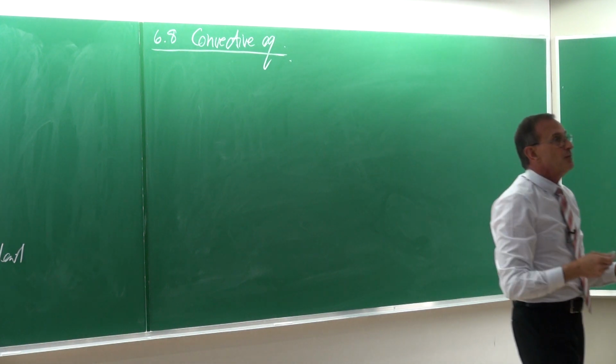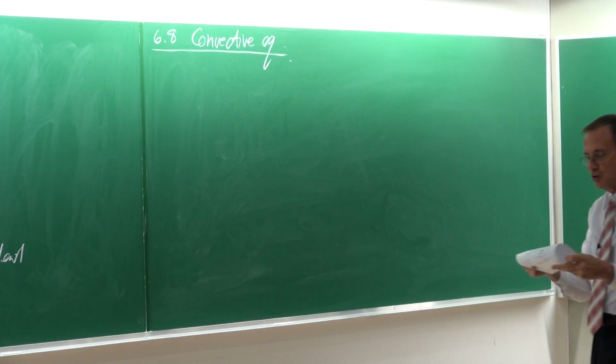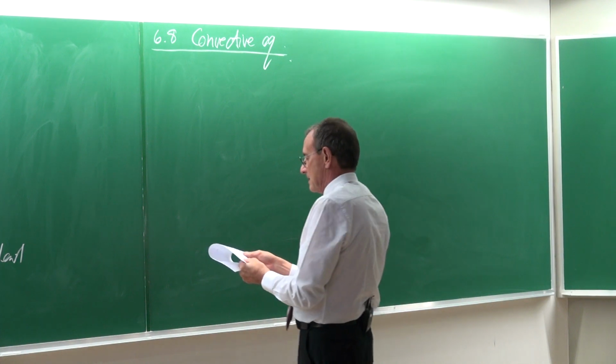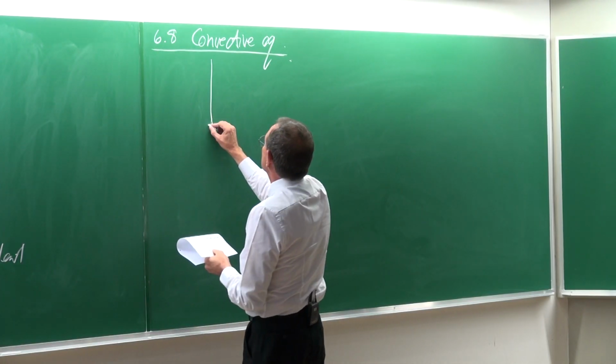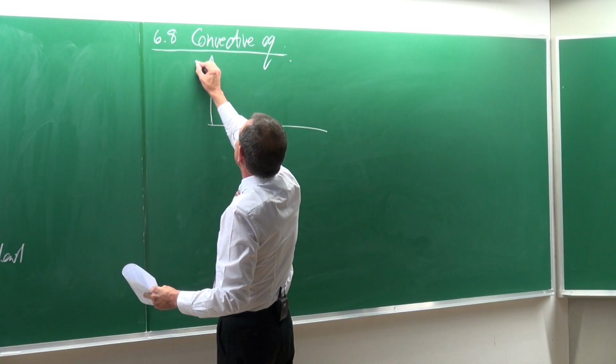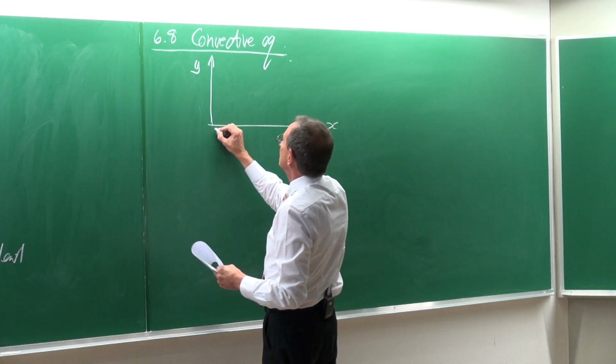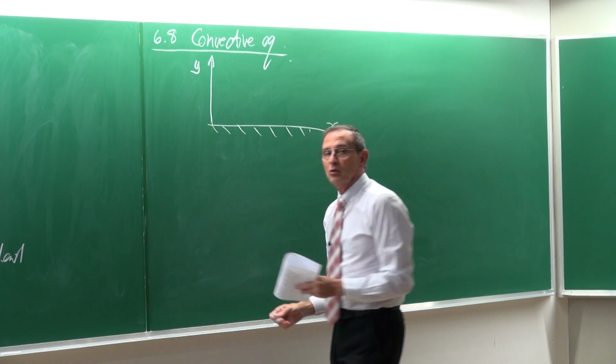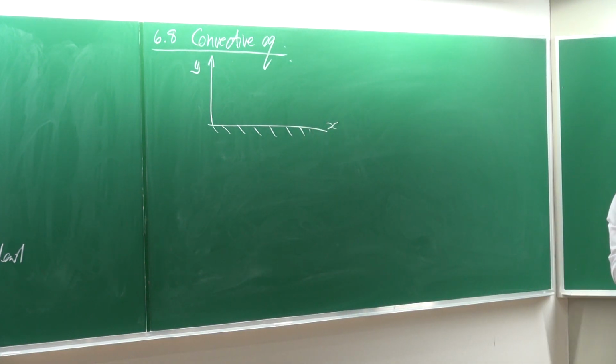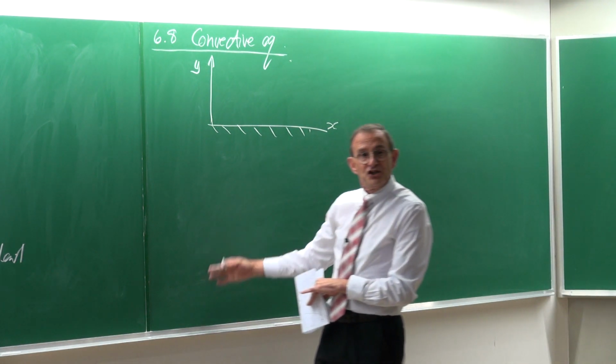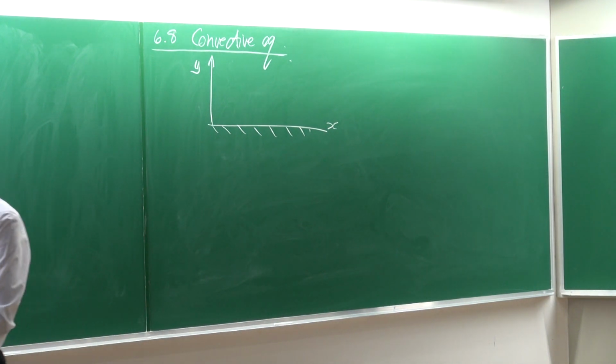Because there's something that can be derived there that is very useful to us in heat transfer. And again, it is considering the same problem that we've considered previously, and that is of a flat plate. Now, why a flat plate all the time, over and over and over again? Because it's the simplest geometry available. The equations that we are going to write down there now are, as you've learned, quite complex. You end up with the Navier-Stokes equations, the continuity equation, and the energy equation in 3 different directions.